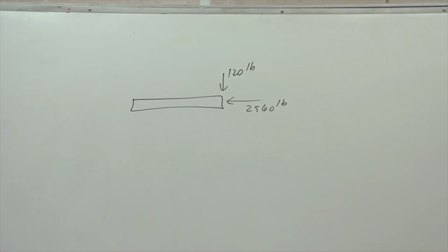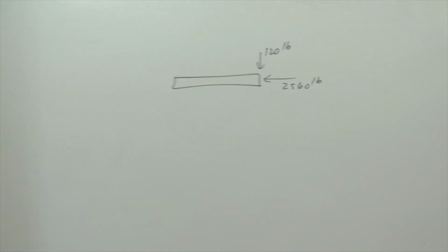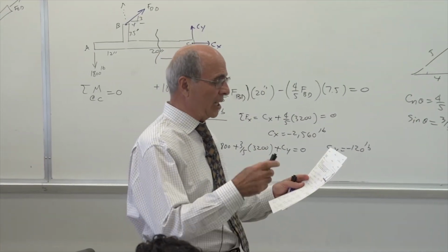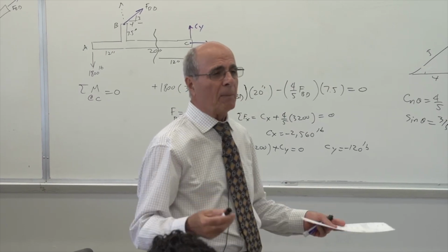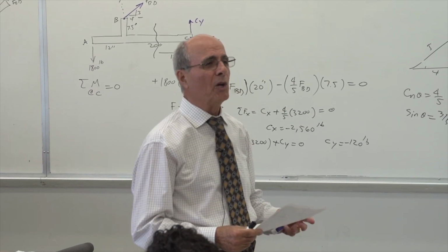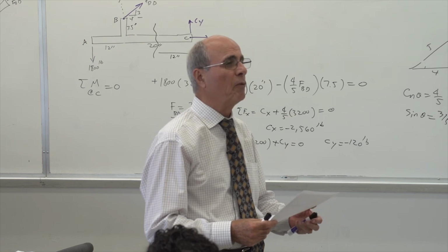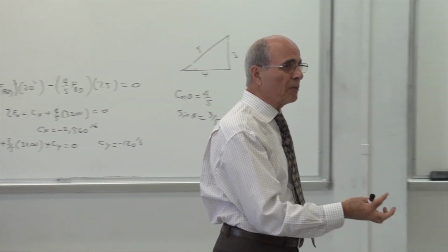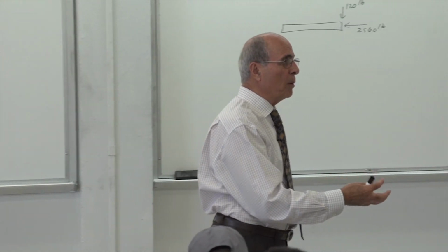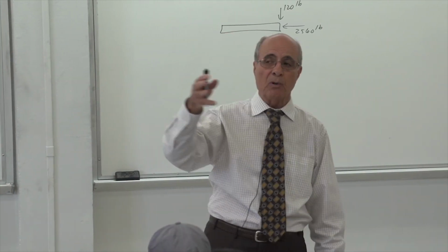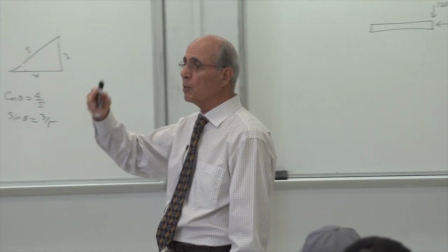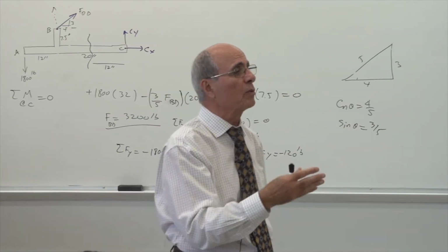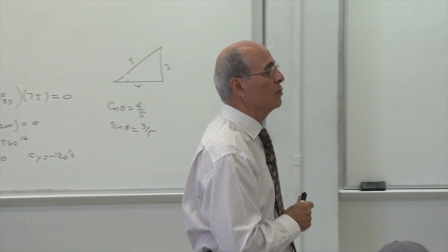Now I'm asking you to calculate the internal forces. Many people call them AX, AY, MA, I don't know. That's a no-no. We already defined our forces. The forces should be in the form of normal force, shear force, or bending moment. Remember that in the handout that I gave you, I said, look at this in the 2D problem. Look at the first handout. There is a picture there. And that's what you were doing in all your first few homework. Calculating that.